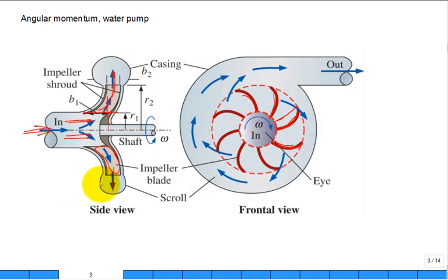And then when it comes off the tip out here off the edge of the impeller, they're showing by the dashed line sequence of positions of the tips of the impeller. The water is sort of slapped out, thrown out. You can see the velocity vector of the water they're trying to illustrate. It's then caught in an increasingly large region, a volute region, and then there's a cut right here, and it's thrown out, and that's a water pump. There's lots of water pumps.